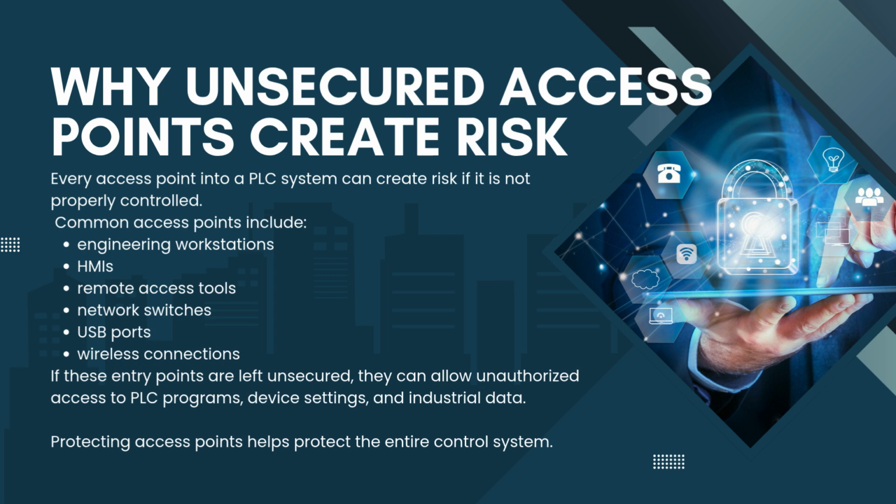Now let's take a closer look at why access points deserve so much attention. Every access point into a PLC system can create risk if it is not properly controlled. Common access points include engineering workstations, HMIs, remote access tools, network switches, USB ports, and wireless connections. If these entry points are left unsecured, they may allow unauthorized access to PLC programs, device settings, and industrial data. A single weak access point can create a pathway into a much larger control system.